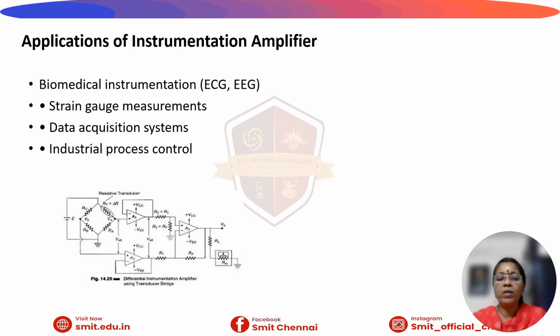Hence, the tiny millivolt signal from the bridge is fed directly into the high impedance input of the three op-amp instrumentation amplifier. The first two op-amps provide nearly infinite input impedance, ensuring the bridge circuit is not loaded down, which would cause measurement errors. Transducers often use long wires that pick up 50 to 60 Hz hum.